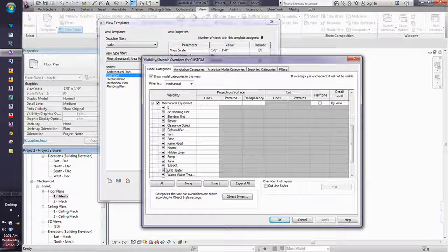This is one of the areas that people just don't do enough of. They don't go in and look at breaking things down. I will tell you that I used to have a lot of breakdown for things like air terminals and electrical fixtures. I had things like receptacles defined as subcategories. I actually backed away from that some. The only ones I put into subcategories right now are mechanical equipment and electrical equipment because their definition is broad. It covers a lot of different types of components. Like mechanical equipment to me can include things like bar screens, filters, vortex grit separators. Can you imagine going in and saying, yeah, it's all mechanical equipment? You want to break it down and have a little bit more control over it that way.